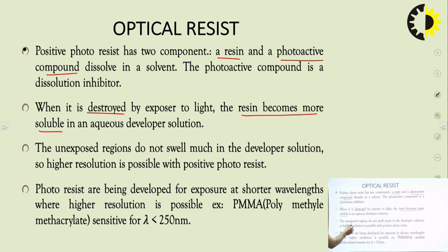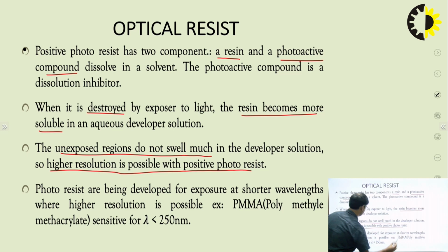The unexposed regions do not swell much. And here we obtain a higher resolution in case of positive photoresist. And positive photoresists are being developed for exposure at shorter wavelengths where higher resolution is possible, for wavelengths as low as less than 250 nanometer.